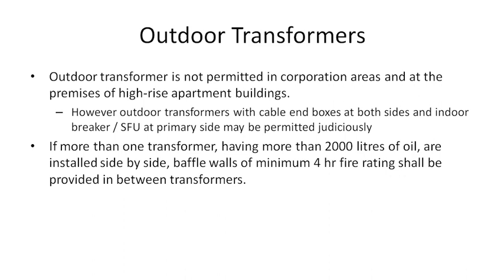Then, if there is more than one transformer and it is an oil-filled transformer having more than 2,000 liters of oil, installed side by side, there shall be baffle walls of minimum 4-hour fire rating provided between the transformers. The reason is that transformer oil is a flammable material. If, for some reason, there is an explosion and the transformer oil starts burning, it must not affect the adjacent transformer in any way. So between these two transformers you will use fire-rated walls, which are rated for a minimum of 4 hours. This 4-hour fire-rated wall is a wall that will not be damaged even if there is intense burning for 4 hours. So that has to be installed in between these transformers.